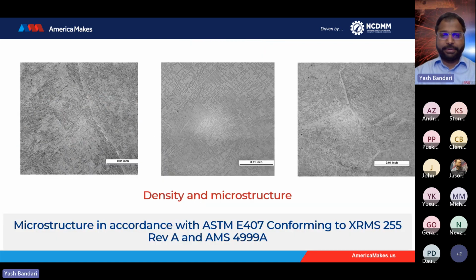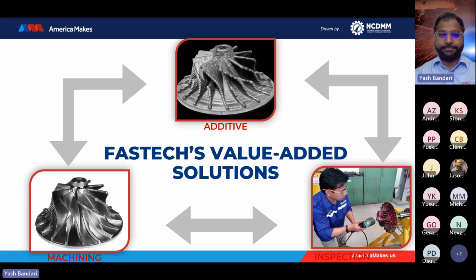Even from a microstructure and mechanical property standpoint, as I said, we spend a lot of time developing and refining the process parameters for printing these components, and we always conform to the ASTM standards on the defect validation or on the microstructure and mechanical properties.